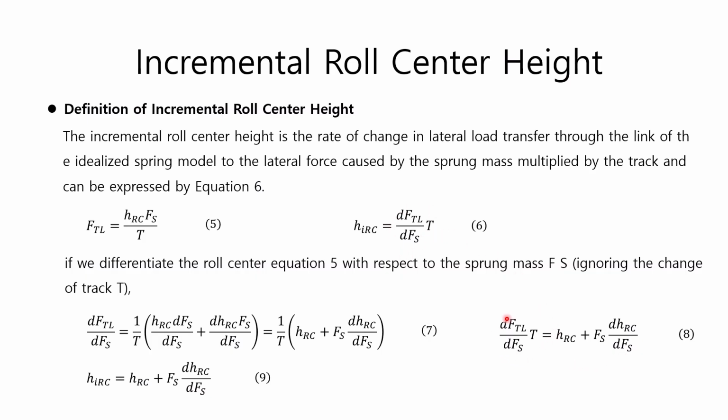From equation 9, we can see that the incremental roll center height, HIRC, is equal to the original roll center HRC plus the change in roll center height due to lateral force. The last term of equation 9 indicates that the lateral force affects the roll center height. Let's illustrate this graphically.